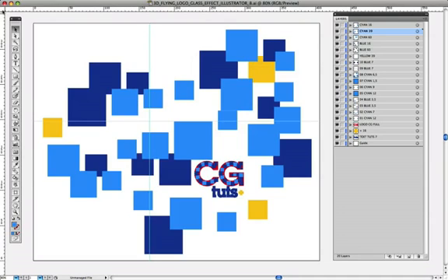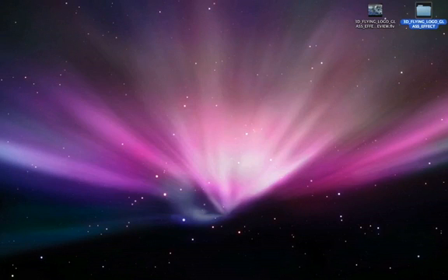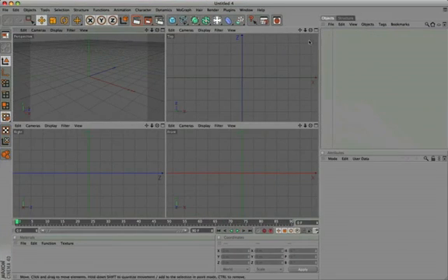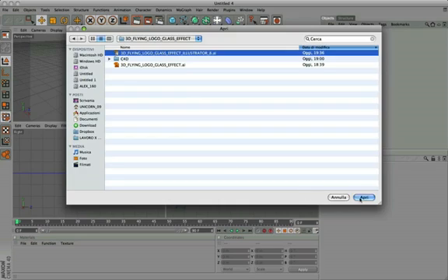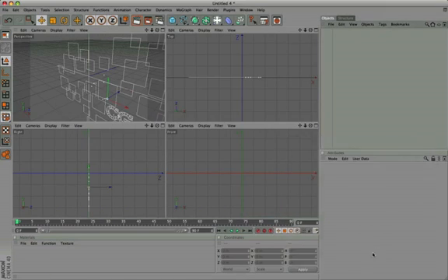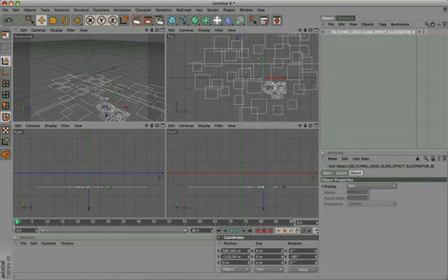We open the rulers with the command R, and drag from the upper left corner to the point where the two guides cross. So we set the 0. In this way, we match our guides made in Illustrator with those of our 3D program. We open Cinema 4D and import the Adobe Illustrator file with File, Merge Object. Click OK. We rotate our object to -90 in the P rotation coordinate. Copy the value of the Y coordinate and paste it in the Z coordinate.